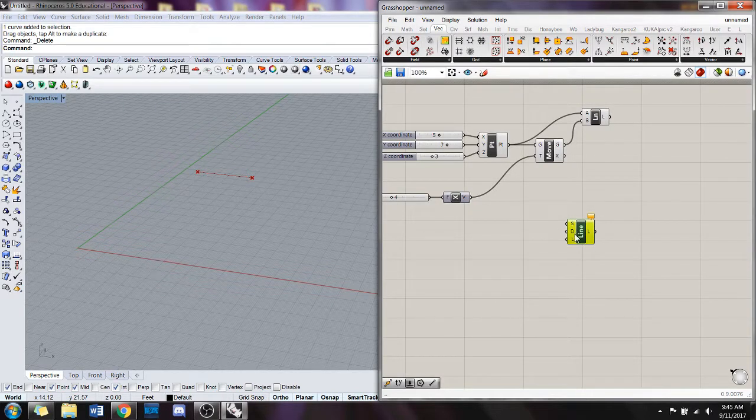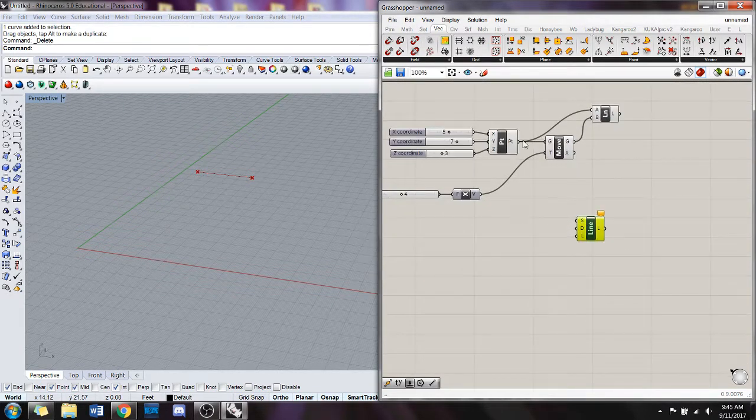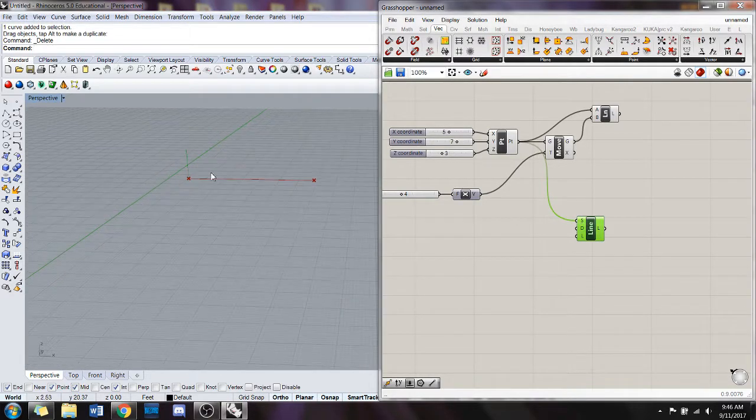So the line SDL, we're going to do the same thing. Going to give it a start point. See, it's going to default to be in the Z direction, 0, 0, 1. And it's going to default to 1 for the length. And I'm just going to plug this same move in X in. And it's going to ignore that length. It's just going to take the direction, not the distance. Then I'm going to plug that 4 in, and we've drawn the same line now with a different kind of line component.